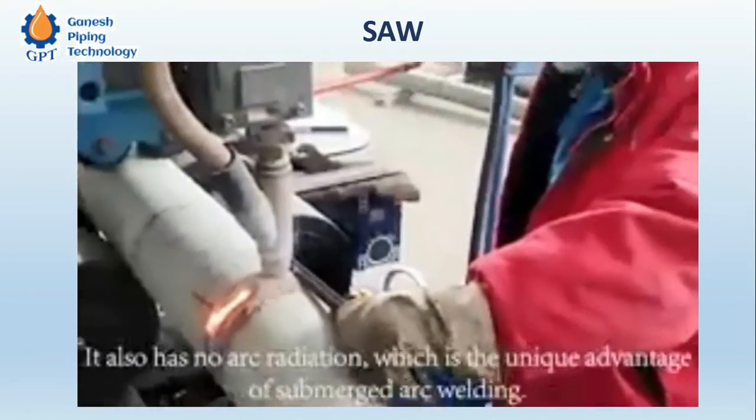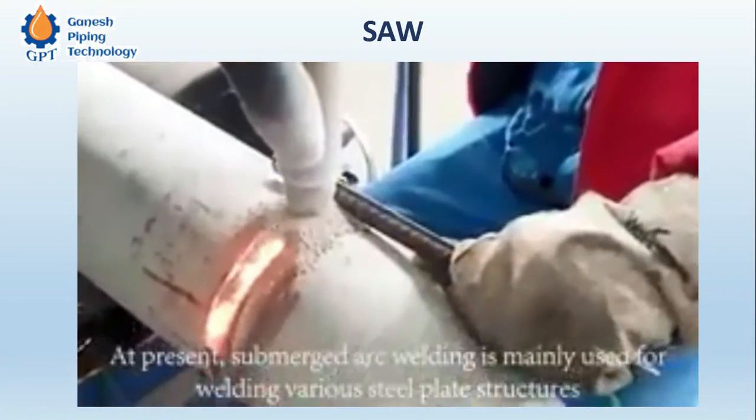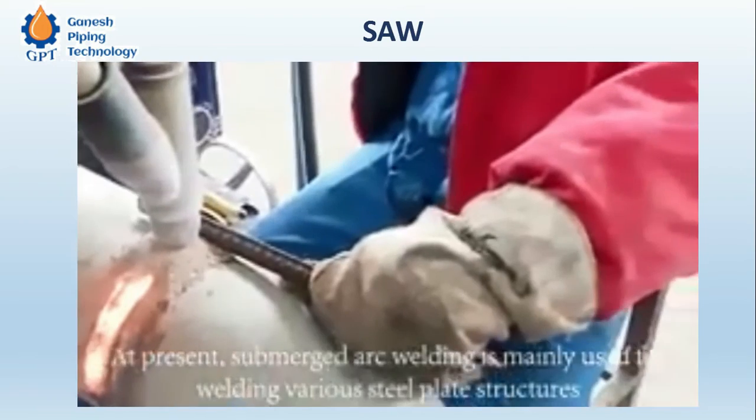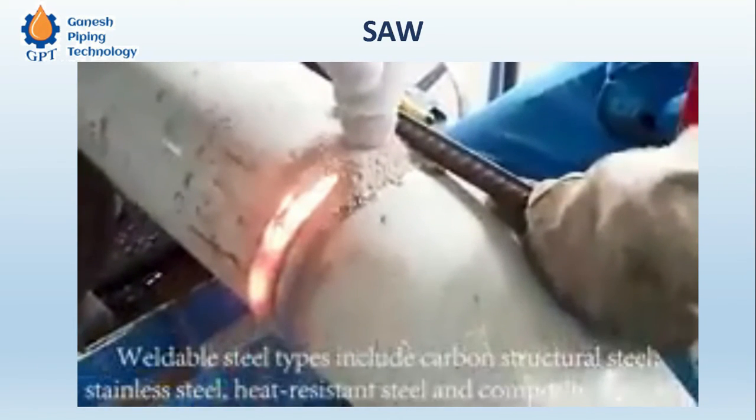Okay, and the speed of the filler metal, that is the speed of the wire, is controlled by the welding machine. So we can see here there are two nozzles. One is the welding nozzle, and surrounding that we have a hopper or the conical mouth from where these flux granules come out. So this is the best example of a productive welding process, submerged arc welding.